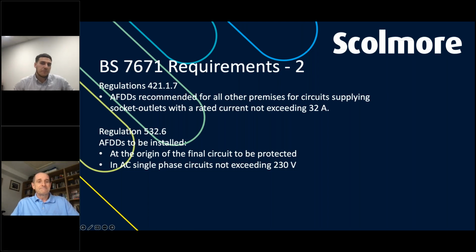You've got to convince a lot of people. I know that, but I'm old enough, Jake, to remember when RCDs were first introduced as a recommendation, and then they were required to supply a socket if you were going to supply equipment used out of doors, then required more and more, and now they're mandated. Just everywhere, even on lighting circuits in domestic premises.